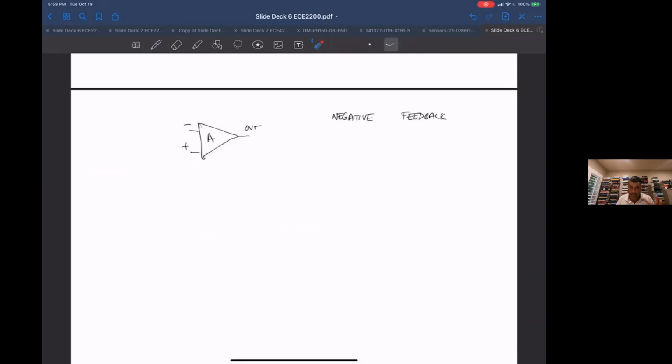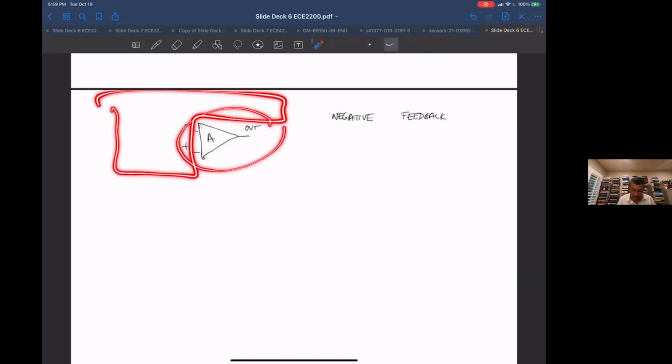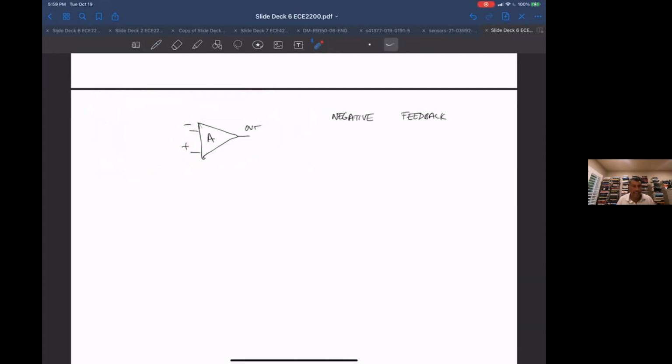This is a very hard concept to get your head around. So you can get very precise performance. It doesn't mean you're attenuating stuff. It's a technique to use the output to make this overall, whatever we're going to make, a stable, reproducible thing. It's called negative feedback. And typically, you want negative feedback in analog design. It's very commonly used, and very important to get precision.